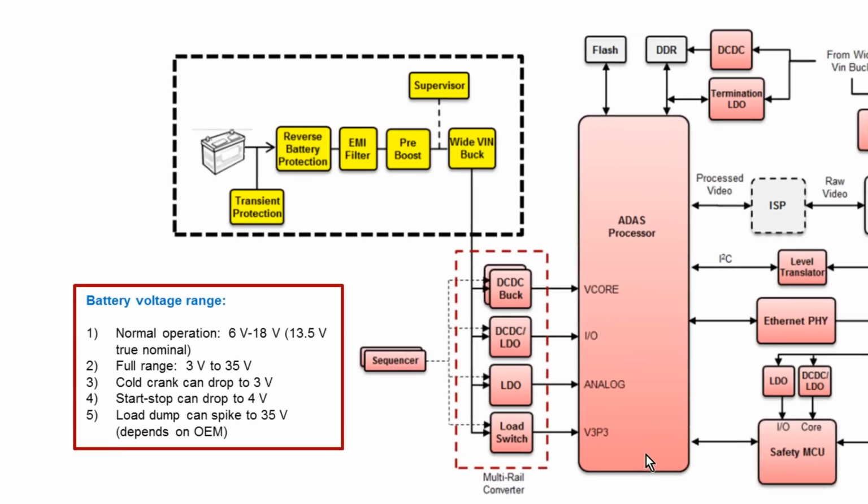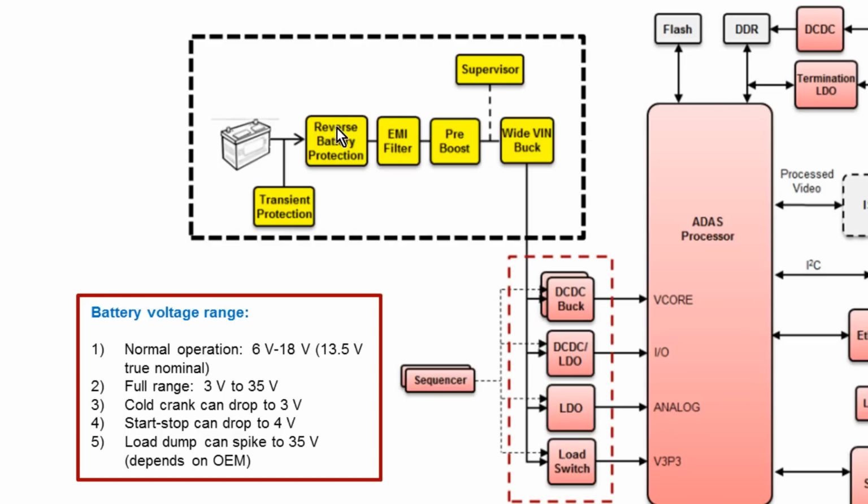This is a generic block diagram of an always-on automotive system in all battery conditions. So what are the key features of the block diagram? The first feature is that the system must maintain a constant output voltage over the full DC range of battery condition specified in the OEM standard. Here the VIN can go down to 3.2 volts, simulating a severe cold cranking condition, or the input voltage can go up to 18 volts, simulating the upper range of normal battery operation.